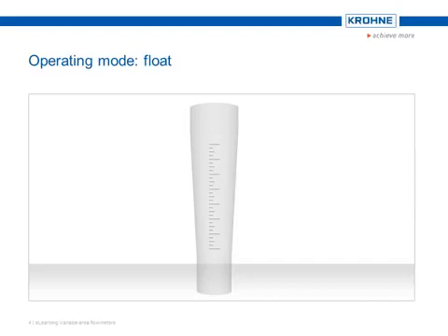The physical operating mode shows that the position of the float is a flow indicator. With glass cones, the flow rate can be read on a scale on the measuring tube itself. With metal cones, the float is not visible, so they have a magnetic transfer onto the pointer.